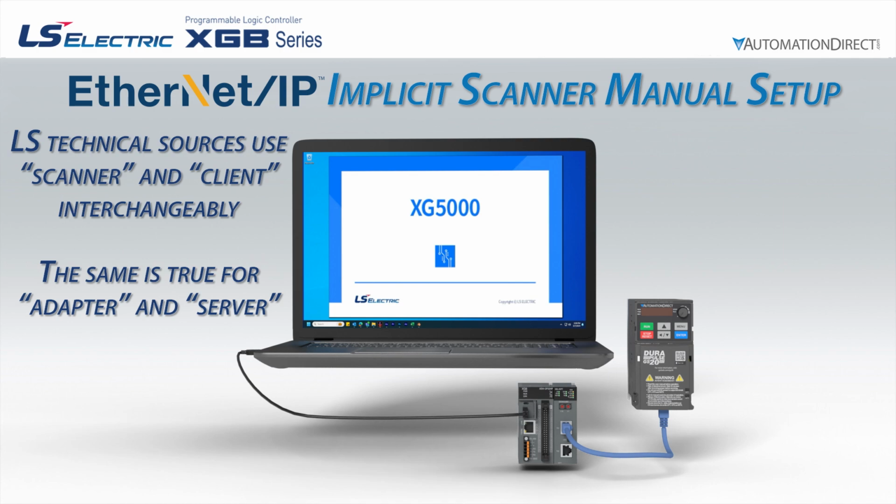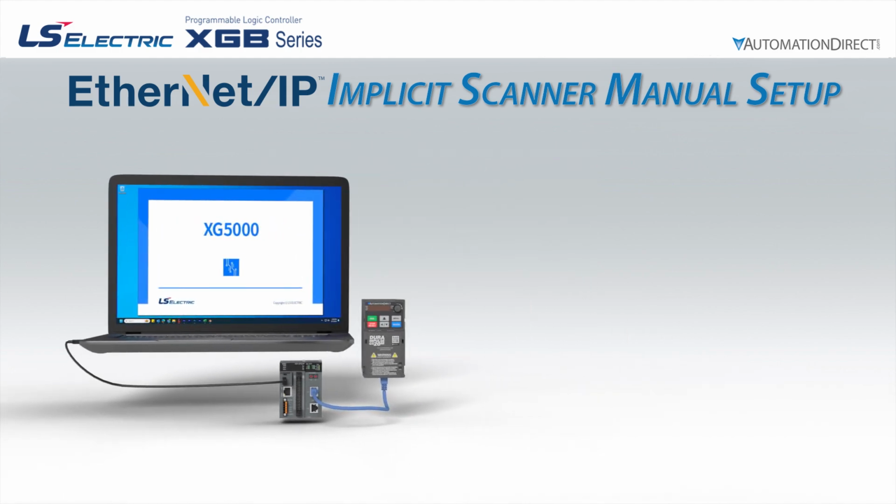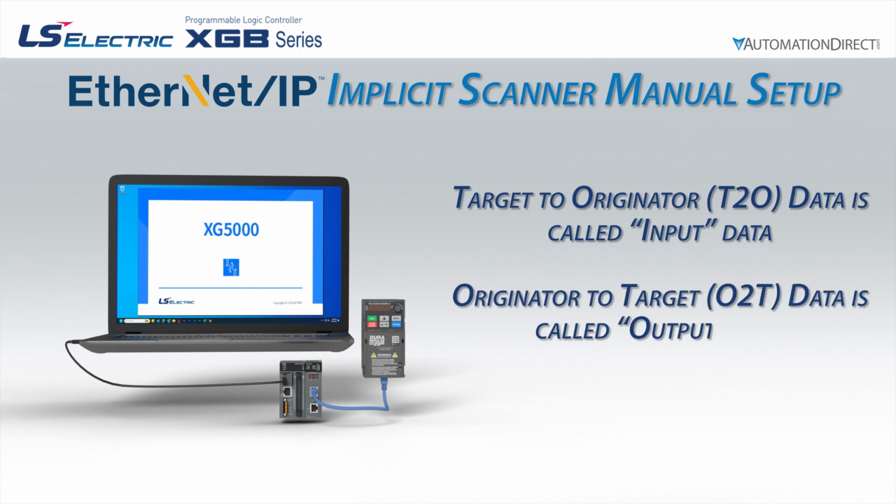It is also important to note that data can move in two directions for Ethernet IP. It can go from the scanner or originator of the message to the adapter or target. It can also go from the target to the originator. As such, target to originator, or T to O data, is called input data since it provides incoming information to the controller, and originator to target, or O to T data, is called output data since it provides outgoing information to the adapter.